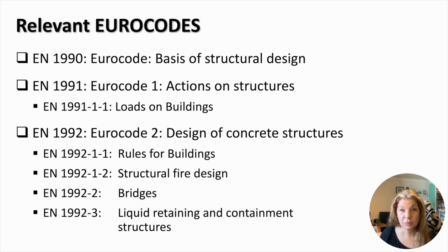Eurocode 0 establishes principles of design, Eurocode 1 defines loads on structures, and Eurocode 2 defines the principles of design of concrete structures, including buildings, bridges, reservoirs and dams, as well as design for fire resistance.